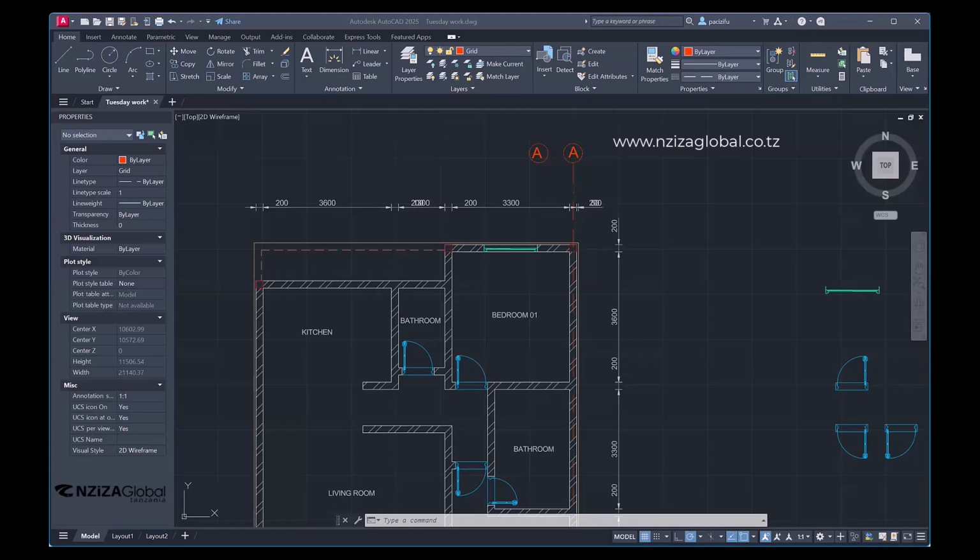We see that we have our grids, which look like this in drawings. You can see we have grids here like A, B, C, and 1, 2, 3. So this is the one that a structural engineer uses on site to locate the footings and columns, even the beams, ground beams, and the other continuous structure elements.